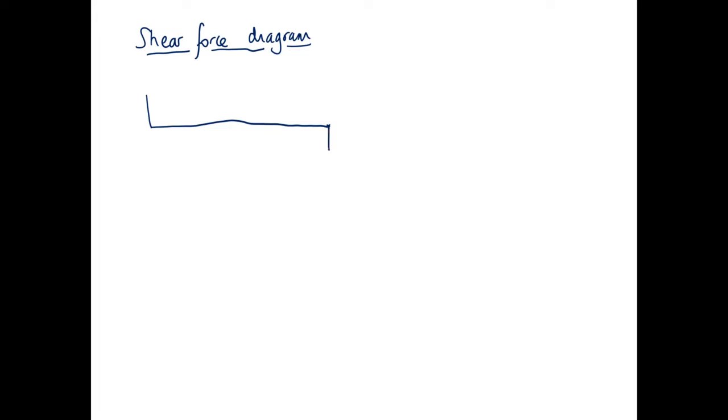So we're going to have a constant change in shear force as we go down through. It's just going to be the load times the length. That's the total load on the member: load in kilonewtons per meter times the length in meters. That gives me kilonewtons. And then we know that half is going to go into the left-hand side, and half into the right-hand side.